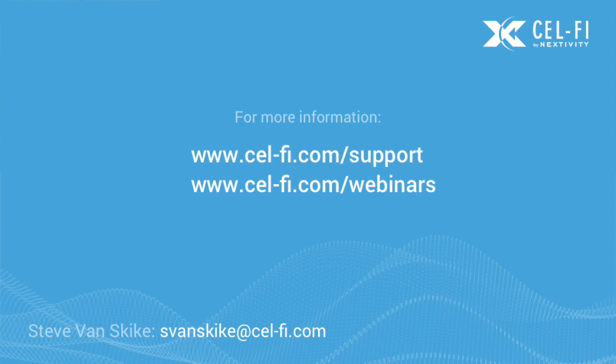So I always have to put a lot of effort into that site survey. If I go there with my phone and I'm using one of these apps for the different operators and I see poor signal to noise ratios, then I'm not going to use the omnidirectional antenna. I'm going to plan on using something highly directed to clean up that problem. But if I go to a site and I see 5, 10 dB through everybody's channels, then an omnidirectional donor antenna will be just fine and a lot easier because you don't have to aim it.